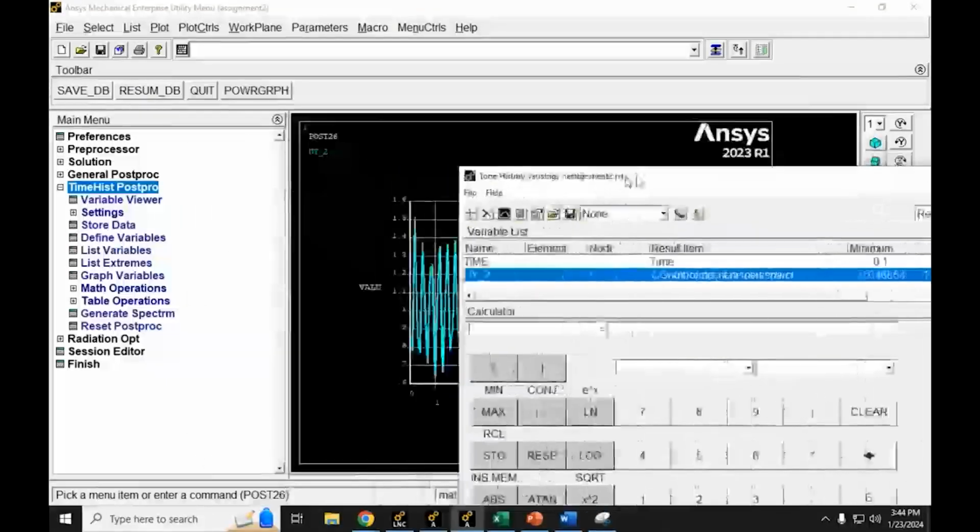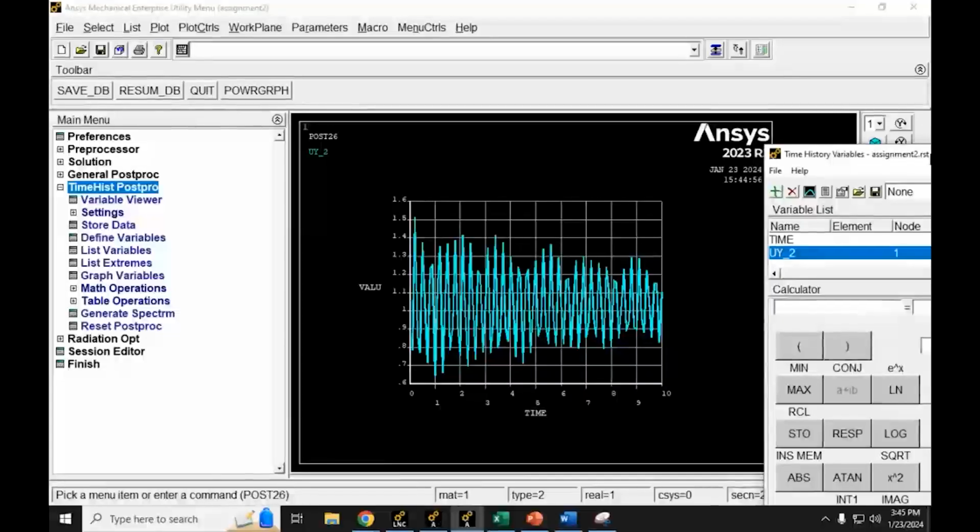And then you have to move this thing off to the side again. So this is what the response of the structure looks like. It's kind of bouncing up and down. It's actually going positive, negative, when you apply this load. So this tells you need to add some dampening to the system. There'll be some natural dampening just because these connections are a little bit loose. There'll be friction in these connections, which adds dampening to the system.